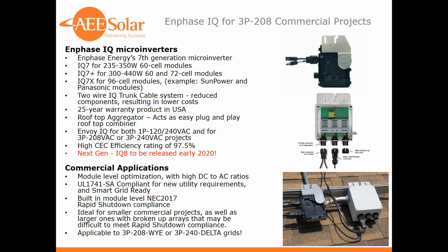We're highly hoping that they'll be on schedule to release their new IQ8, which will have advanced functionalities, hopefully at the end of this year or early 2020. So for commercial applications, again, we can put fairly high-level wattage modules to these. They're SA compliant. We have built-in rapid shutdown. And these really should be considered for your smaller projects or for carports and for constrained roofs that have broken up arrays.